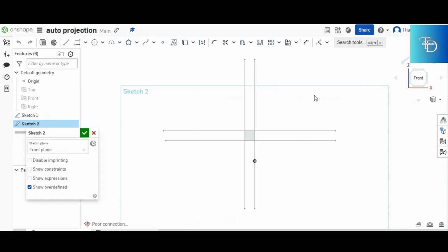Alright, now the first thing that you do before you put your views, you have to create a space and borders for your views. So this is like a Cartesian plane, it's a cross. So when you're creating this cross, you have two parallel lines going downward, and then you have two horizontal parallels. And then the space in between those two lines is 20 millimeters apart. And then the space in between those two verticals is also 20 millimeters apart.